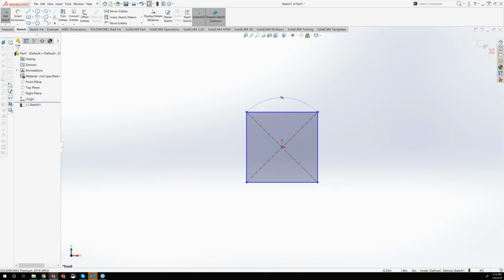So this arc here is approximating what that toolpath is going to be, because as we all know, G-code is point to point. We're going from one location to the next. So in polar interpolation, we're going from this point to this point here, and the only thing we're moving is that C-axis. So by doing that rotation, we get a swing like this, which isn't the straight line that we're